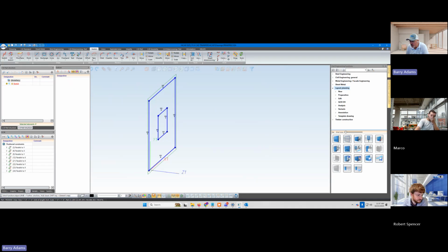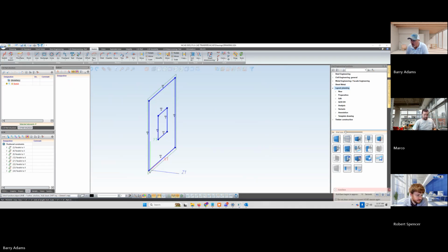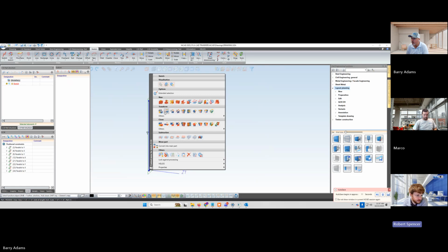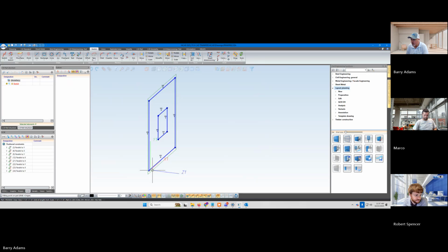All right. What is the process for that? Right click on the sketch. And under transform, you could transform about an edge, or you could go to others and transform about an axis. Which one did you do? I think you just hit move. You wanted to do a rotate one.